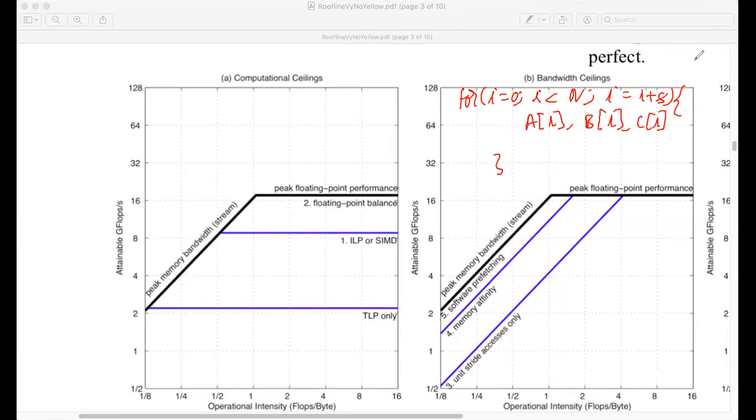It depends on the DDR controller, but many of them do it. But if the stride is big, then you fetch the data and discard all the surrounding data because it's not useful for you. So big strides are bad for you. The net memory bandwidth you can utilize is less.